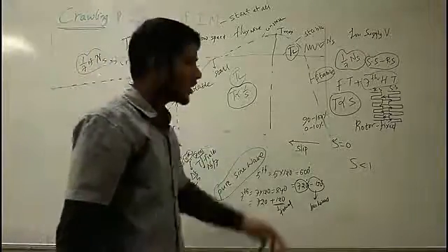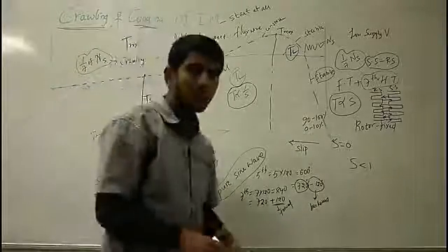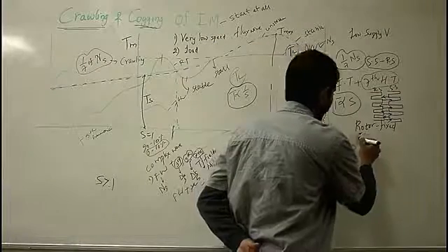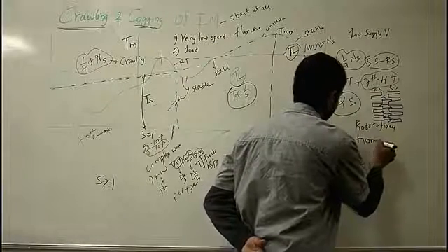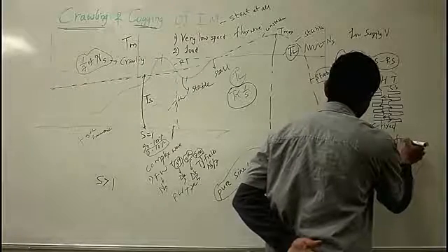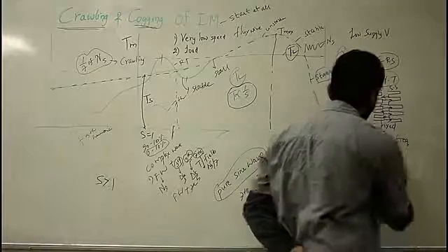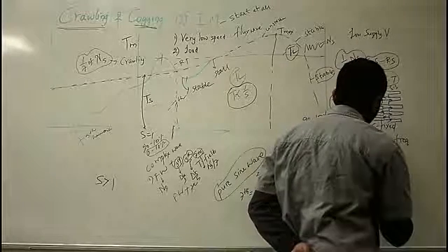Now there is also one more reason for cogging of your induction motor. The other reason is if the harmonic frequencies coincide with the slot frequency due to the harmonics present in the supply voltage.